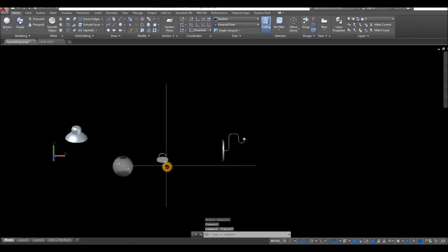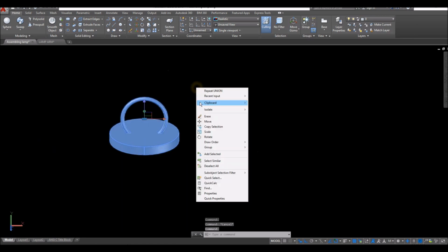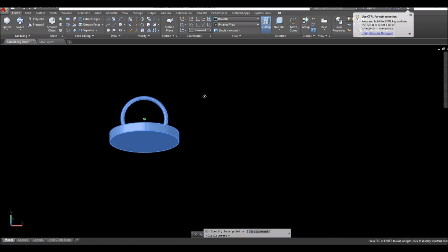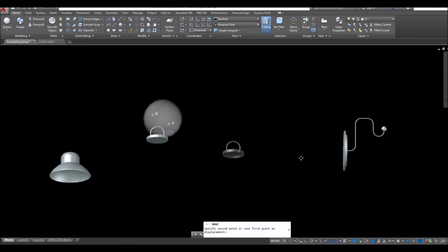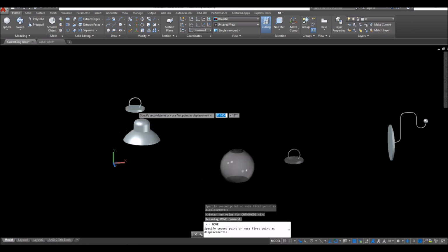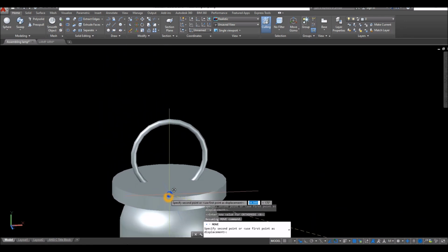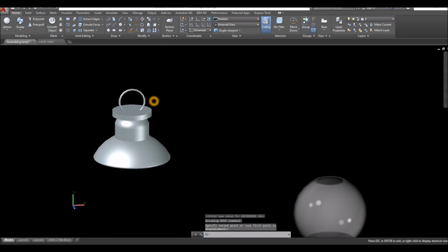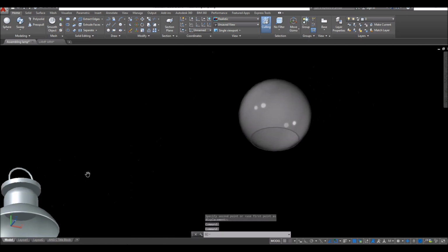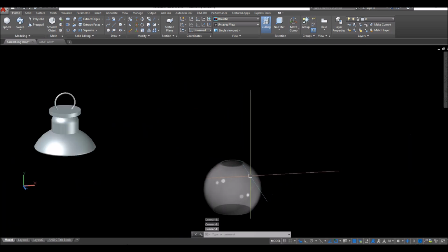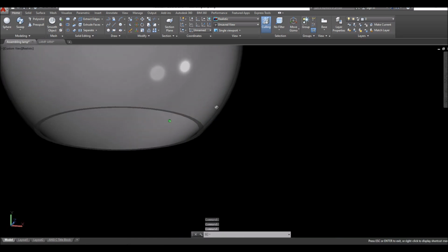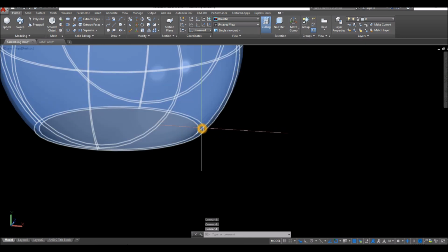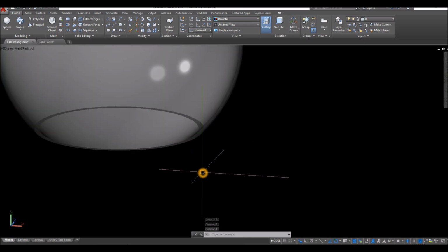The next step is to attach this one. Move. Center of the face. You can see that it's the center because of the blue color. Snap that. And attach it to the center of this, to the tip of this holder. Next thing to do is move this one, the shade. By the way, the shade in our model extended from the tip here for a certain unit.